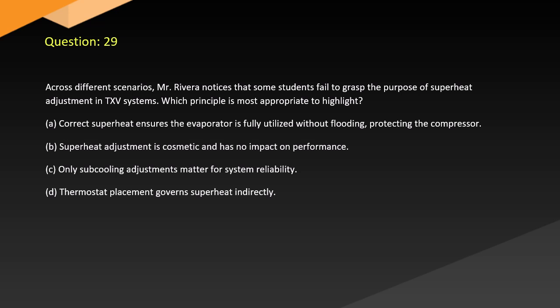Question 29. Across different scenarios, Mr. Rivera notices that some students fail to grasp the purpose of superheat adjustment in TXV systems. Which principle is most appropriate to highlight? A. Correct superheat ensures the evaporator is fully utilized without flooding, protecting the compressor. B. Superheat adjustment is cosmetic and has no impact on performance. C. Only subcooling adjustments matter for system reliability. D. Thermostat placement governs superheat indirectly.